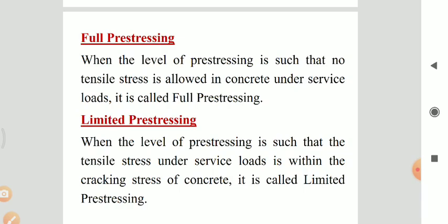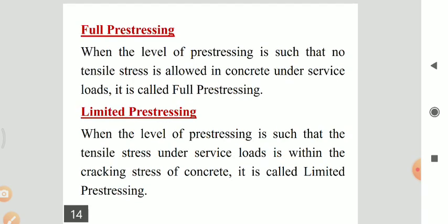Full compression is given to the concrete and zero tensile force, under the service load, meaning the maximum load coming through the life of that particular beam or slab.